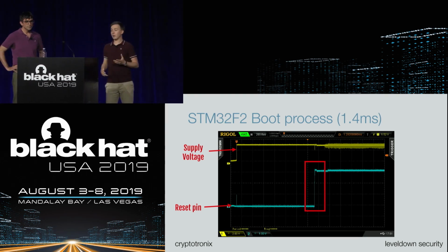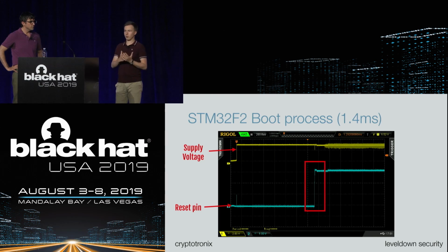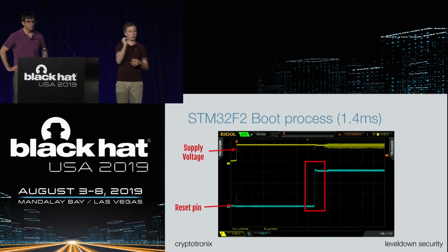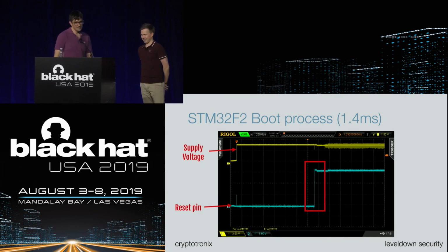But basically, the first 1.4 milliseconds of the boot, nothing happens, and we couldn't get a reliable trigger because the execution timing was different every time. But then we found out that roughly 1.4 milliseconds into the boot process, the reset pin shoots high, and we can use that as the perfect trigger of when the Bootrom starts executing.